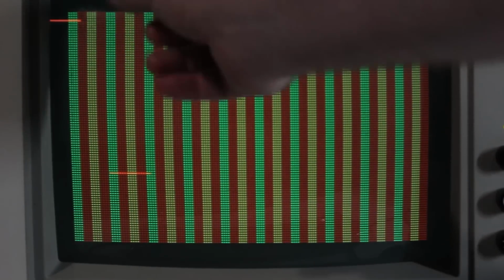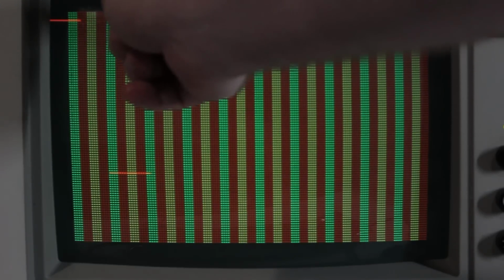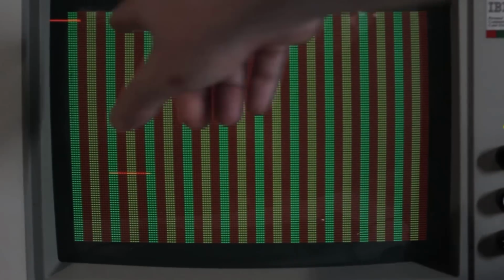And in fact, it's possible to set up a loop with the CPU that is 1 H dot short of a full CRTC frame. And so that means that we can just run that loop a certain number of iterations, and every time it's just going to step back by 1 H dot. And we do that until we're back out of the active region again, and then we know we're in precisely the same place every time that code is run.